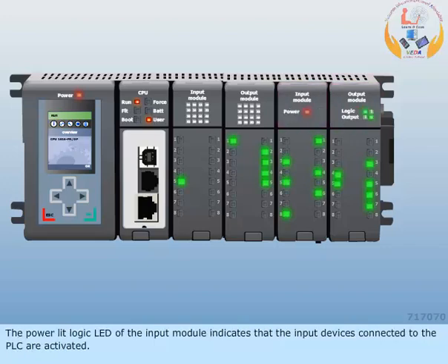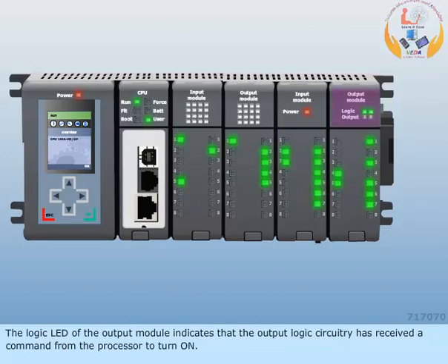The power lit LED of the input module indicates that the input devices connected to the PLC are activated. The logic LED of the output module indicates that the output logic circuitry has received a command from the processor to turn on.